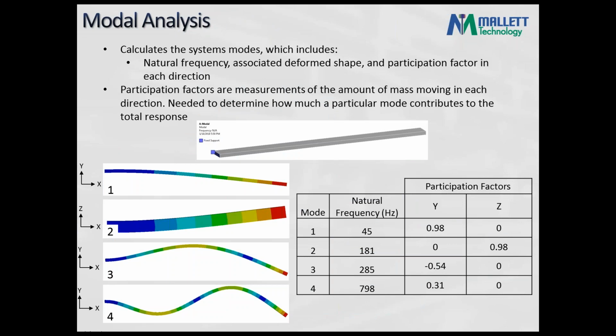So modal analysis, what is the purpose of this? Modal analysis essentially allows for the calculation of a few different variables: a system's natural frequency, the associated deformed shape at that natural frequency, and the participation factor in each direction of that shape.